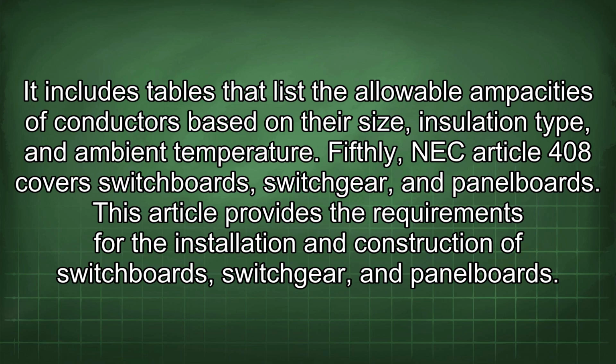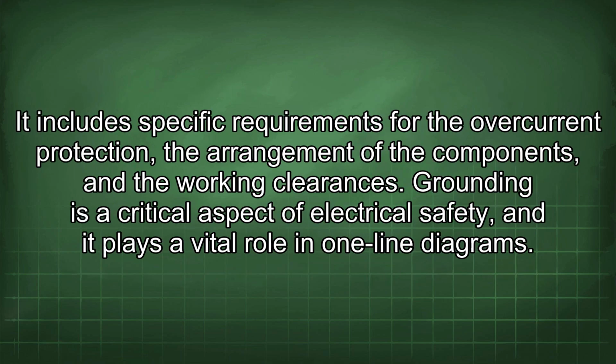Fifthly, NEC Article 408 covers switchboards, switchgear, and panel boards. This article provides the requirements for the installation and construction of switchboards, switchgear, and panel boards. It includes specific requirements for the overcurrent protection, the arrangement of the components, and the working clearances.